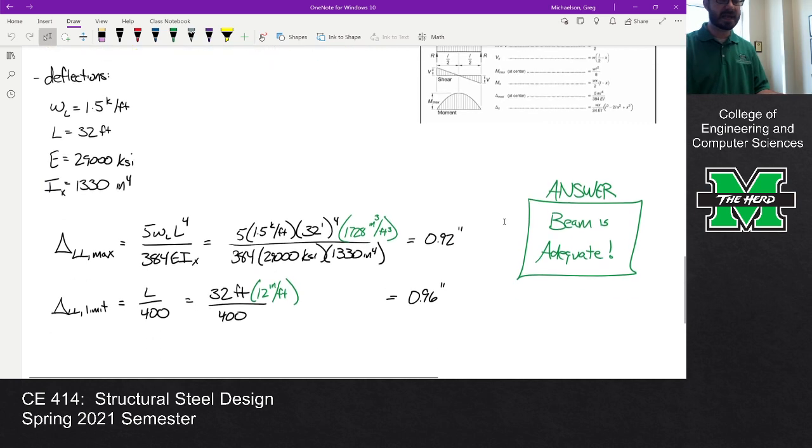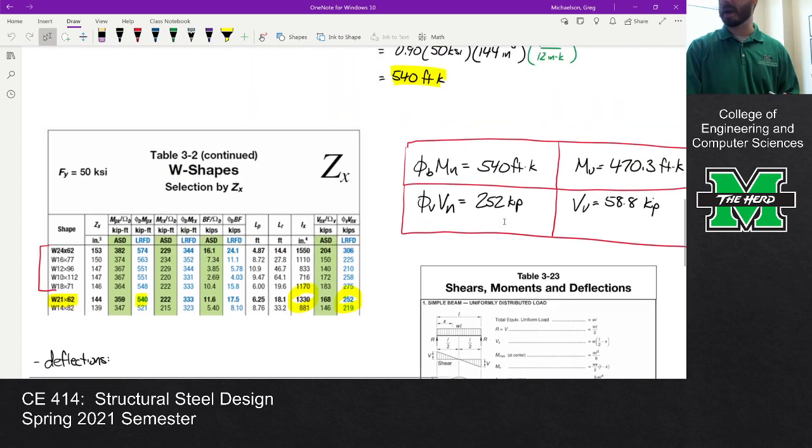This was an example that we did last time, and we were looking at moment, shear, and deflection for a representative beam. Now I'm going to introduce you to some bridge engineering terminology, what's called a performance ratio. We've already done performance ratios before when we looked at efficiencies. We looked at Pu over phi Pn, and so I want to use that to illustrate what's going on with this problem.